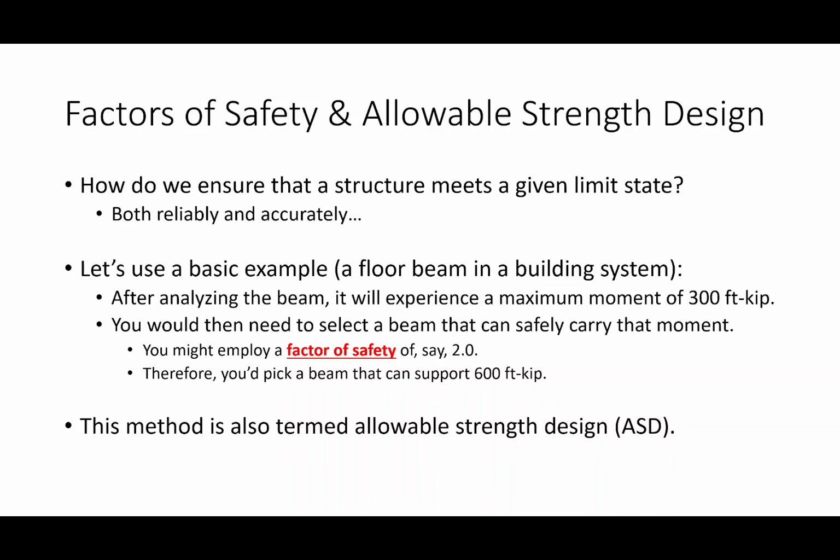That is a design philosophy. In other words, I have calculated loads and calculated resistances, and what a design philosophy basically means is I am adjusting those loads and resistances to achieve safety. And the simplest design philosophy ever is a factor of safety.